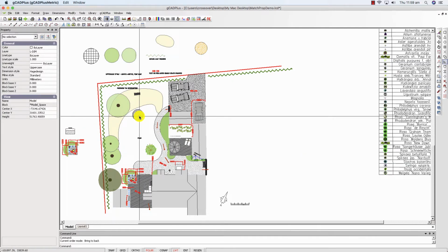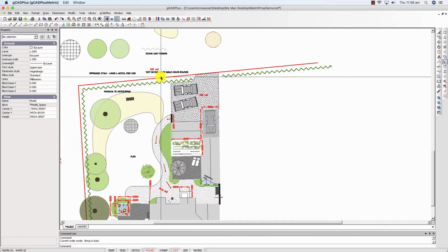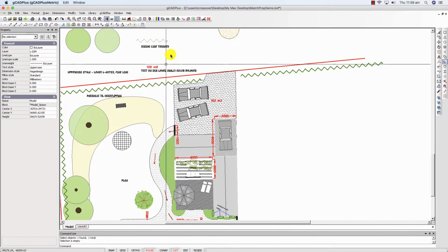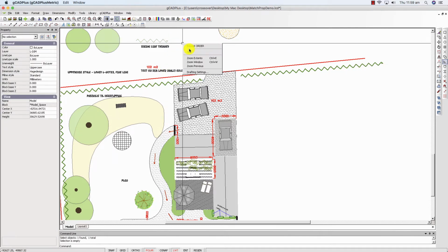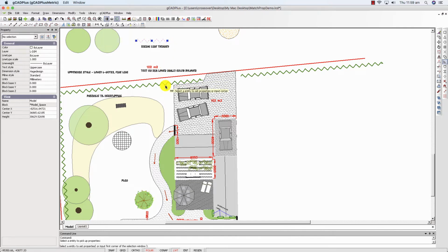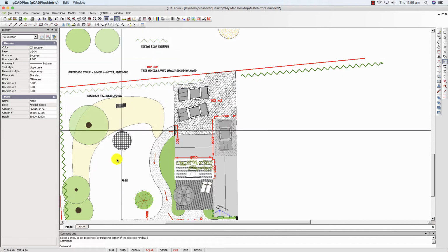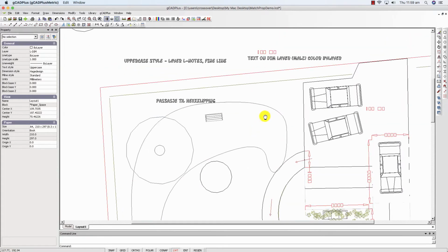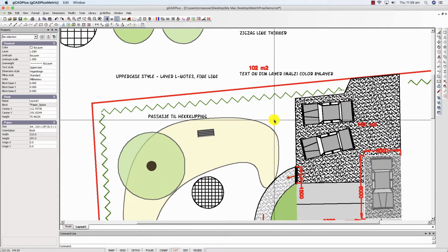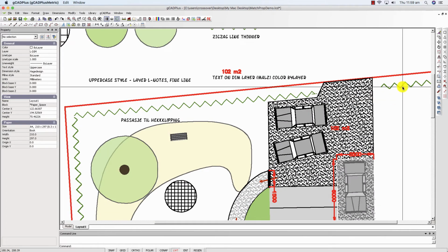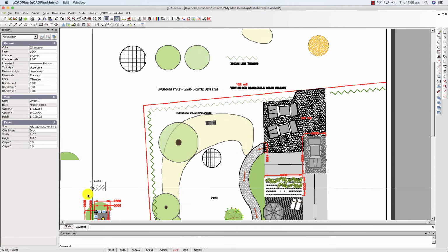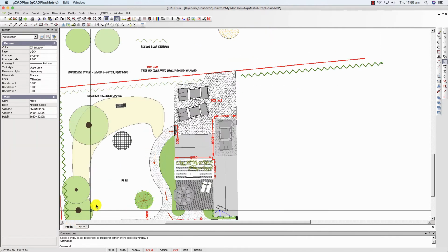Not only text and fills can be matched. Just say you had a fairly thick line type through here, 0.3, you wanted to use a thinner line, so Match Properties, match it like so, whoops, and there we have a thinner line. That becomes important, of course, when you go to a layout space where you may be able to see across. Here's the line that we didn't match, and there's the line that we did match. Let me go back to the model.